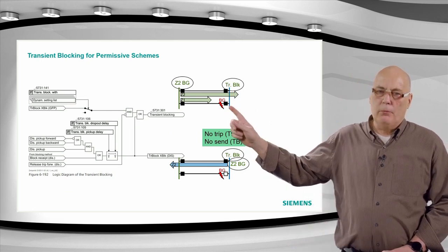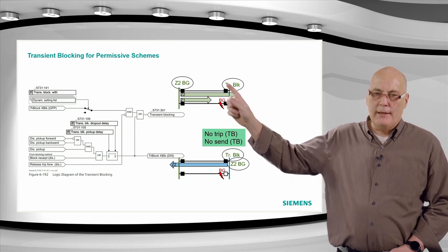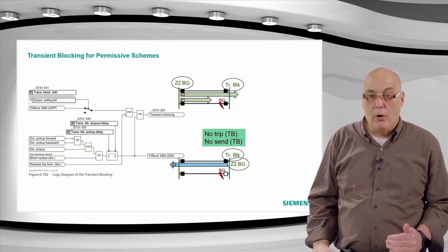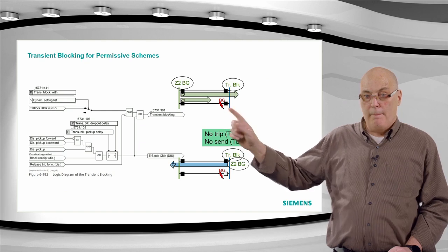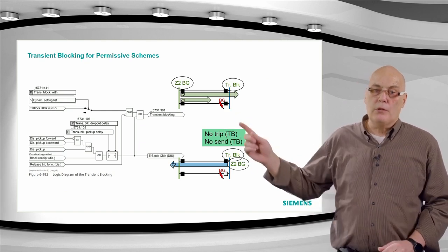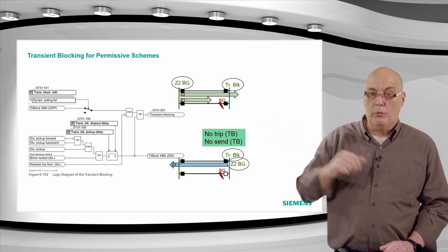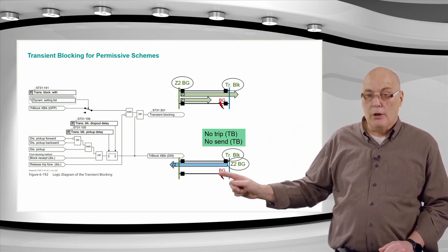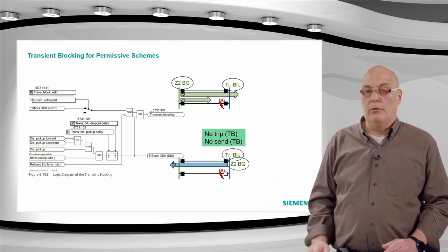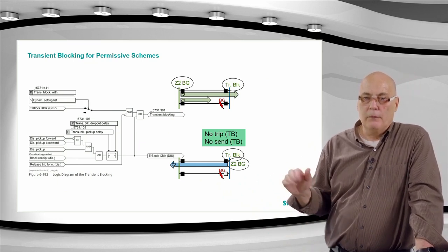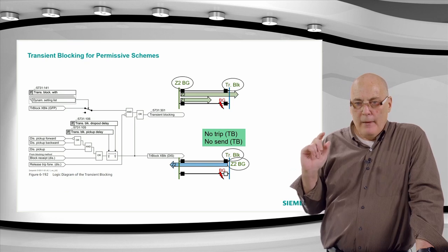At the top, for example, you can see 2 feeders again. It does not have to be a double circuit, but on the double circuit this problem is amplified, or more probable, because of the mutual coupling we talked about earlier on. During the second condition at the bottom, the mutual coupling will pull this fault closer to the relay location, but that's just something else one can talk about, a bit technical.